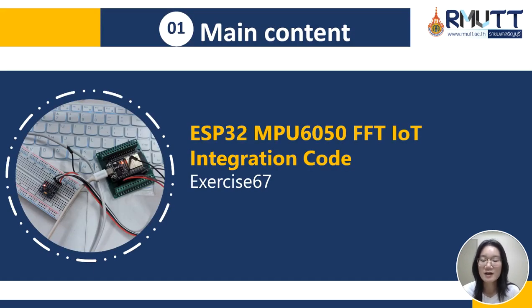Okay, this is part 1, main connect. In this part, I learned how to convert time domain accelerometer data into the frequency domain using the Fourier transform, FFT. I use an ESP32 microcontroller interfaced with an MPU6050 sensor to get acceleration data.